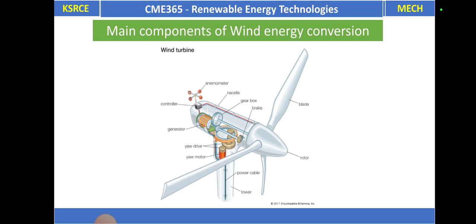The mechanical power generated by the wind turbine is transmitted to the electric generator by the transmission system located in the nacelle. The transmission system contains a gearbox, clutch and braking system to stop the rotor in an emergency. The purpose of the gearbox is to increase the speed of the rotor, typically from 20 to 50 rpm to 1000 to 1500 rpm, which is required for driving most types of electrical generators. The transmission system must be designed for high dynamic torque loads due to the fluctuating power output from the rotor.